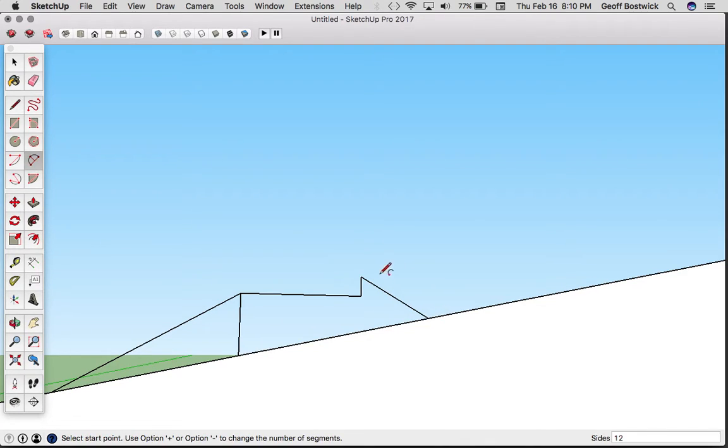So at that point, we want to make a smooth transition from the slope to the angle of the jump. I can do a couple things here. I can just take it with the arc tool, which is A for arc. Most of the shortcuts are pretty intuitive, but you could also use your icons if you can't remember.